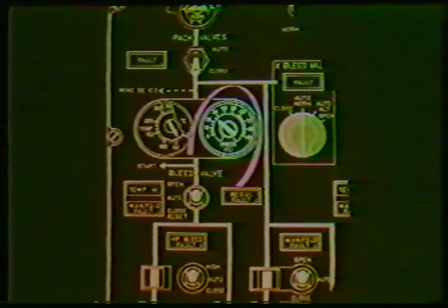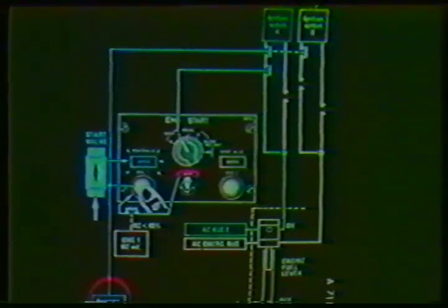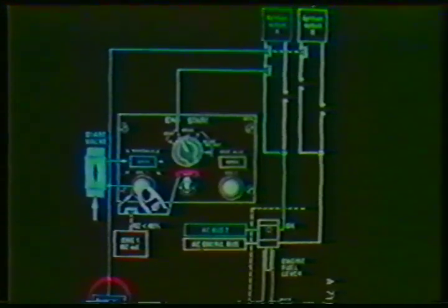The corresponding pressure gauge on the air bleed panel indicates available pressure for starting. When the start push button is depressed, it remains depressed. The start valve opens and air is routed to the starter. The start valve open blue light will illuminate, and the ignition is armed.